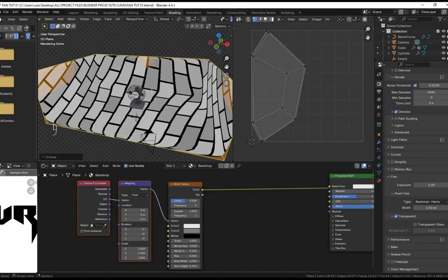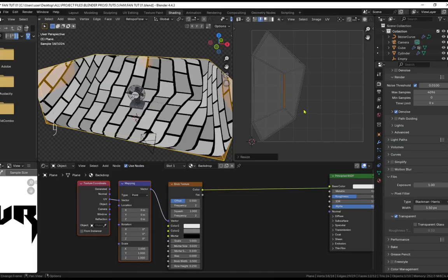Okay, so let's use the angle based unwrapping, and then what you are going to do to fix this is we come to this UV here and change it to edge select mode, and then select this edge over here, and then S to scale it, X to scale it on the X axis, and then 0 to straighten it.